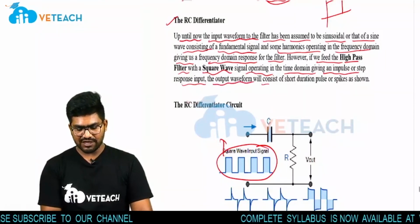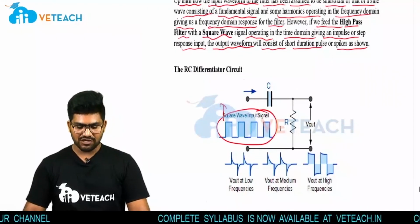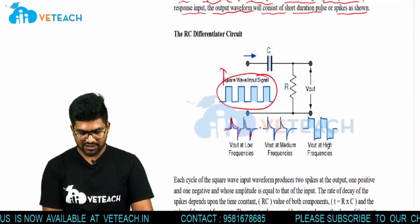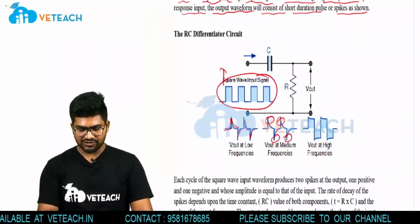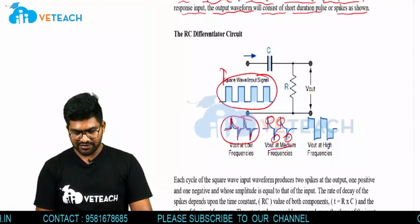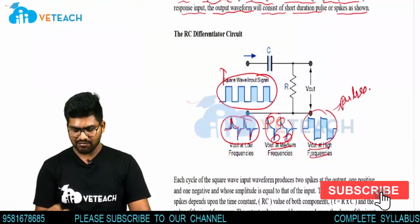The output waveform will consist of short duration pulses or spikes, as shown. So if I give the square wave as an input, my output will have spikes, shown like a pulse with spikes or distortion. So this is the arrangement. At low frequencies we get my output as a pulse with spikes. At medium frequencies it is less pronounced, whereas at high frequencies it becomes a complete pulse type output.